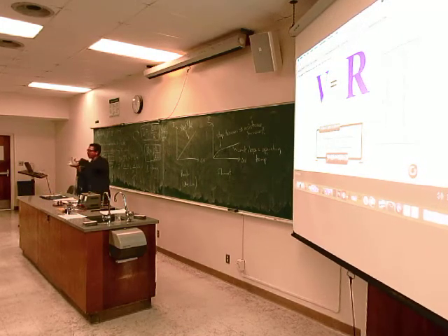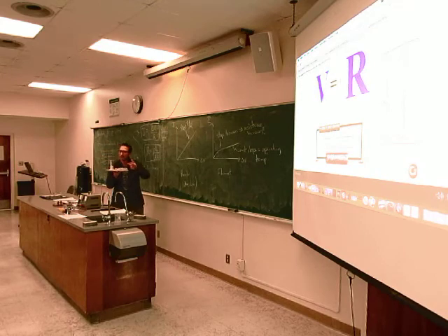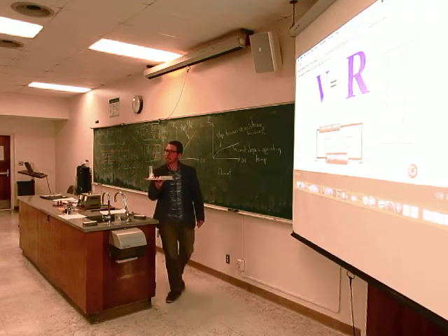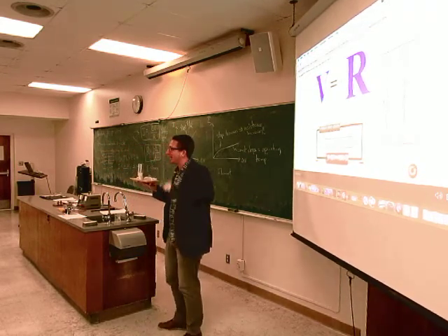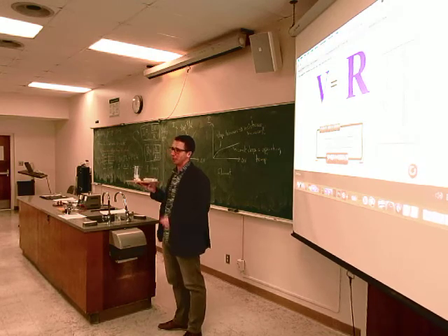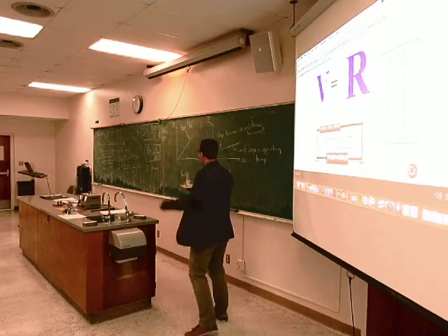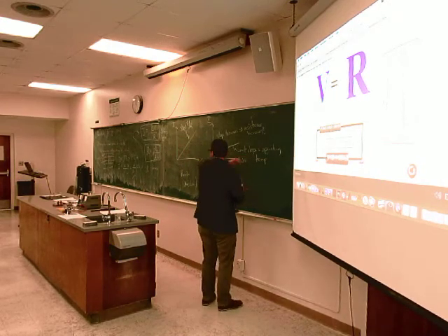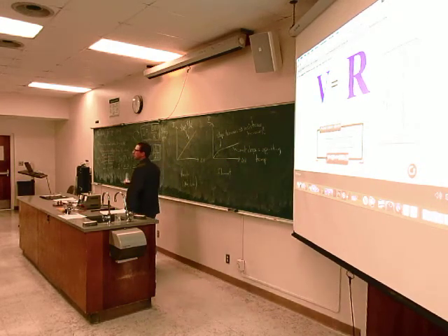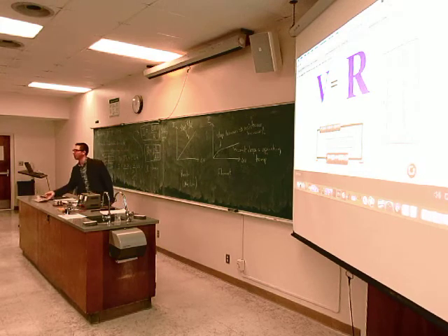if there's not a vacuum around the filament and the filament lit on fire, right, and it's severed, then in a sense it becomes infinite resistance because the wires aren't connected to each other anymore. It literally burns the filament. So in a sense, your current would kind of go back down to zero. You have no current, regardless of what voltage you have at that point.